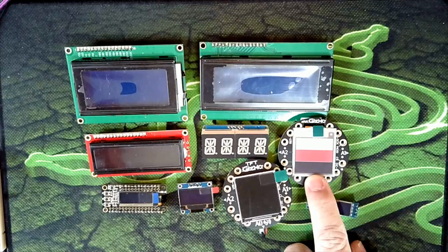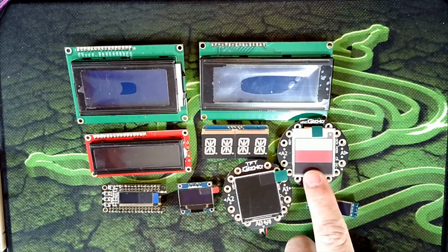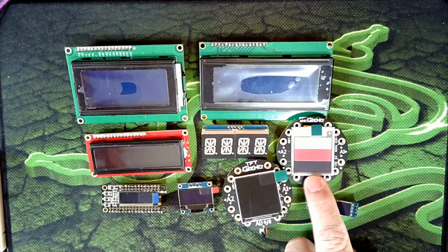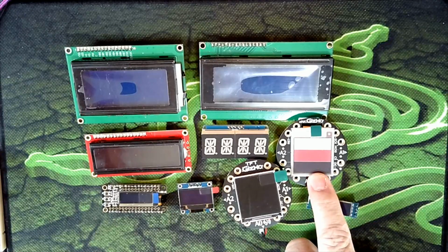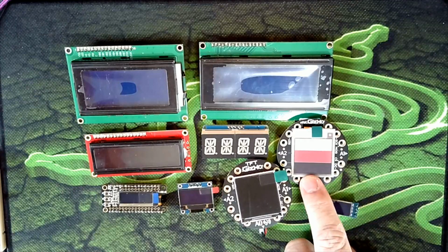So they're very economical to run and take very low power because you only power them up when you want to change the image. Now, they don't change instantaneously like the rest of these do. These do take a couple of seconds to draw the image onto the screen, as it does each color separately. So it takes a little bit more time, but you get the advantage of power saving in between. If you don't need to update your screen often, this is a great choice, and it's great for low power conditions, because you can put your microprocessor into sleep mode. When you power it up, you do the update on the screen and then you power it back down again. So a battery can last you an awful long time when powering devices like this.